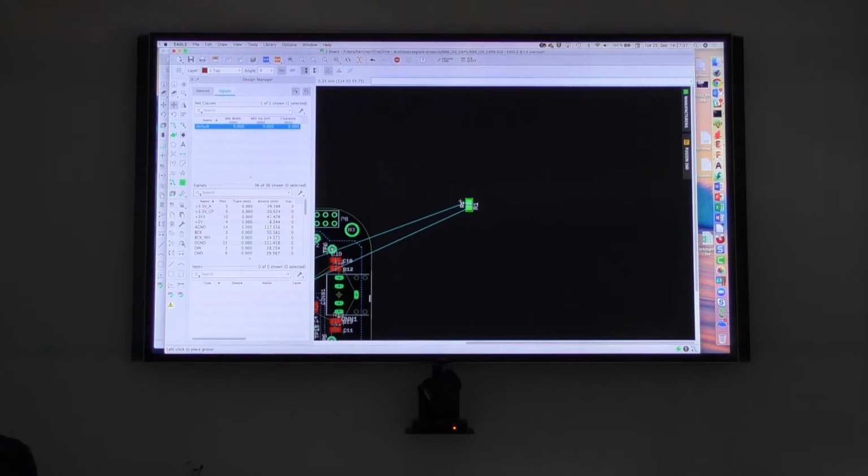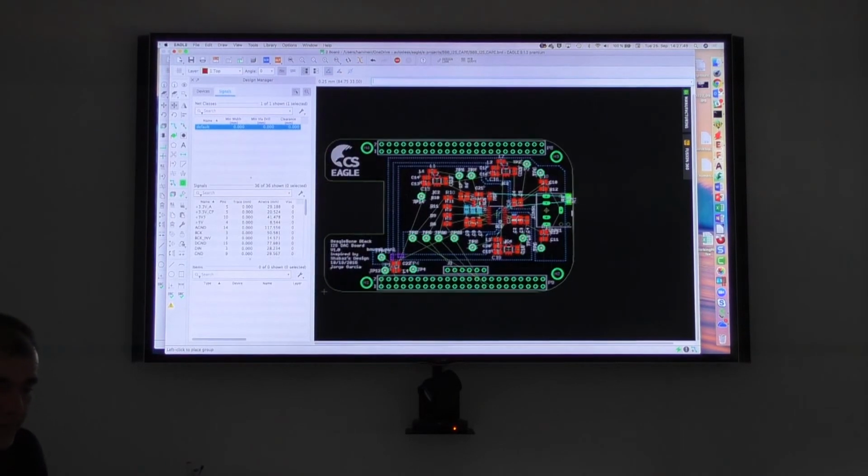If you know your schematic and your board, then most people work this way, because I know I have an IC1, I have a diode 1, I have this and that. I don't have to move around, go back there and change the zoom factor and go forward back. So it's a combination of clicking and typing in the command line that helps in creating a board and makes it more efficient.